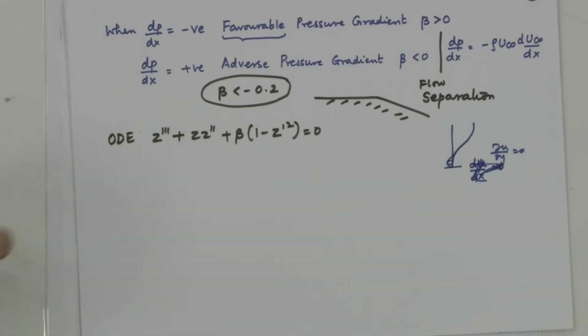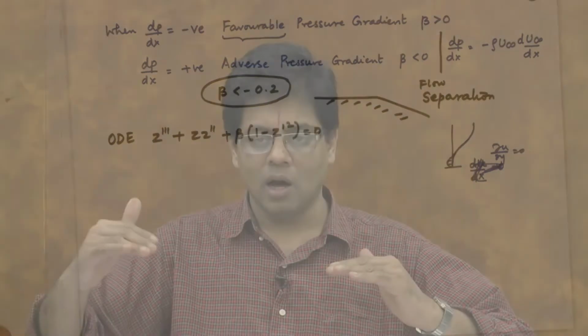So, the fluid is also subjected to a reverse kind of action, and the velocity of the flow is a direct indicator of the momentum. If you look at the left-hand and right-hand sides of the Navier-Stokes equation, dP by dx is positive, so the quantity on the left-hand side starts to decrease, and therefore you would reach a stage where the flow is no longer able to sustain itself, and you would see separation of flow occurring.